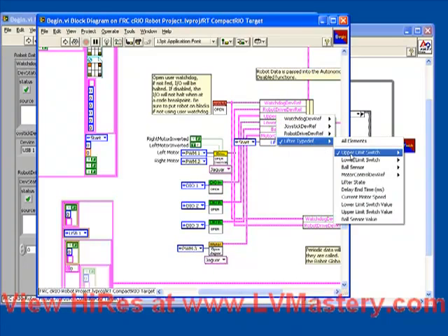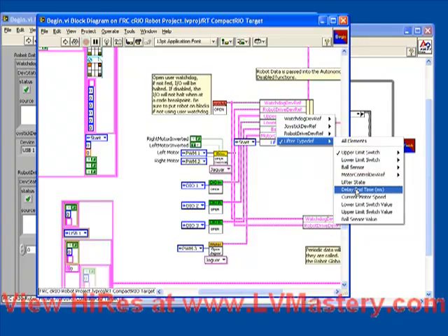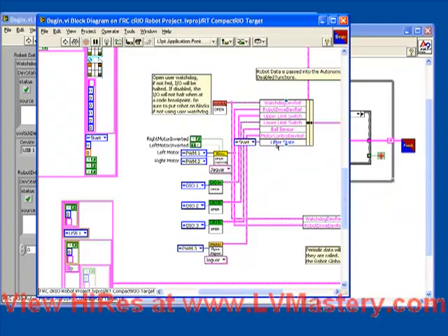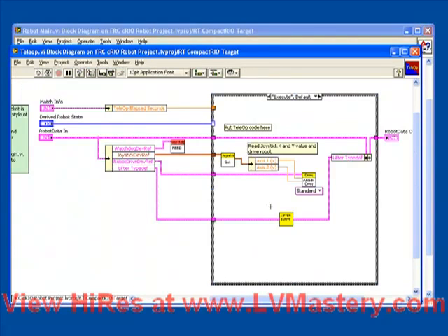That lifter type def contained the device references for the hardware, as well as an internal state, an internal delay timer to keep track of when to move to the next state, as well as keeping track of the output values, the current motor speed, limit switch values, and the ball sensor value. So after hooking all that up in the begin VI, we then went into TeleOp and created a new sub-VI called the lifter sub-VI. That lifter sub-VI, as its input, took that type def which we just created. As its output, it gave an updated value of that type def, which then got bundled into the robot data.